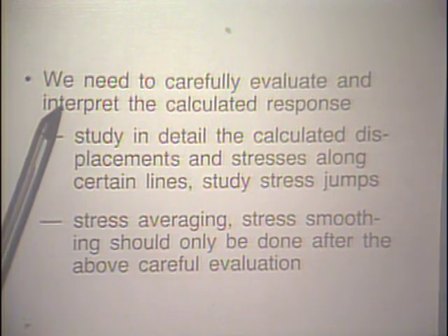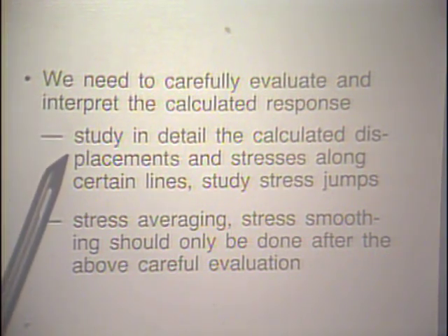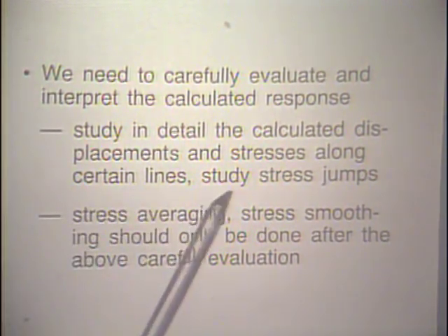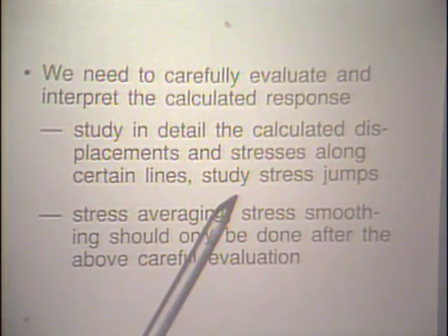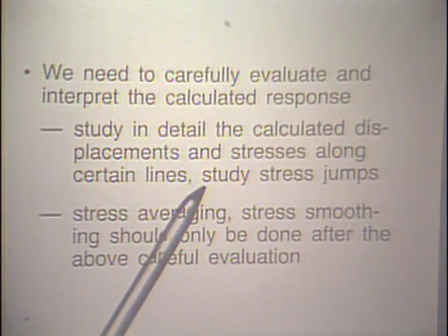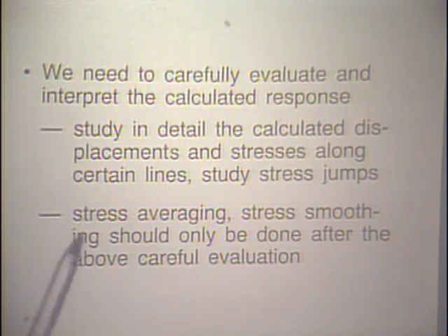Once the analysis has been performed, you want to very carefully evaluate and interpret the calculated response. You want to study in detail the calculated displacements and stresses along certain lines. In particular, look at stress jumps. We pointed that out already in an earlier lecture, and we will do so in our example solution again just now.